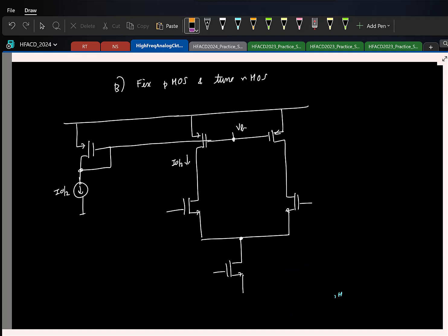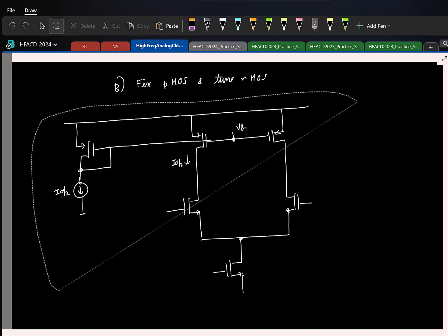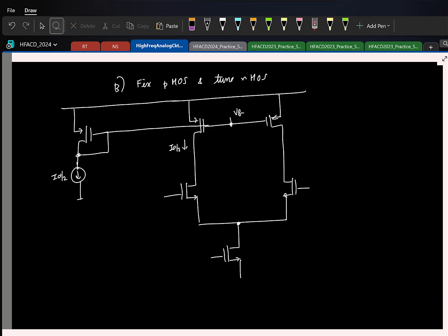Okay. So if you were to control the source voltage, you can't put an op amp there, but of course you can't go and connect it to ground. So let us say you will put some element here that will incur some drop. Okay. Now let us say the nMOS current here is some IN, and let us say this is the outputs. If I find that, say, the nMOS current is smaller than the pMOS current I0 by 2, what can you say about the common mode voltage? I am pushing in more current here than the current that is getting pulled out, so the common mode increases.